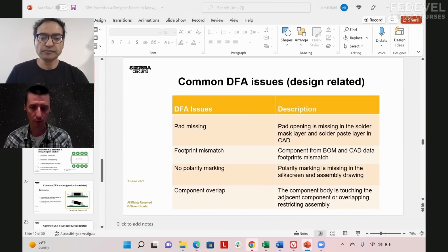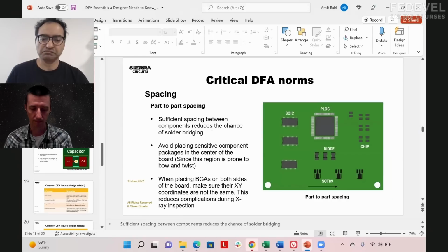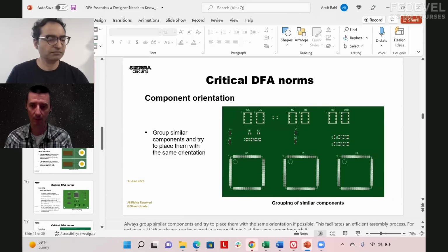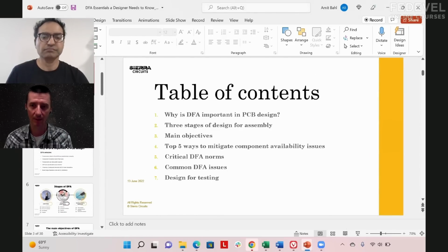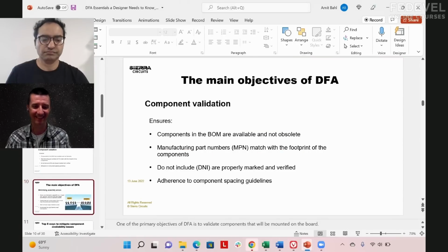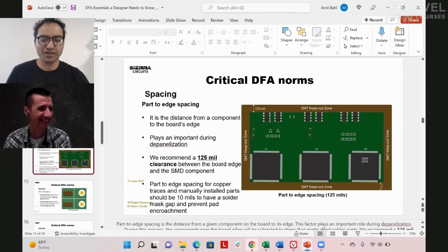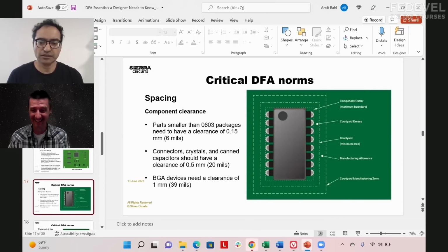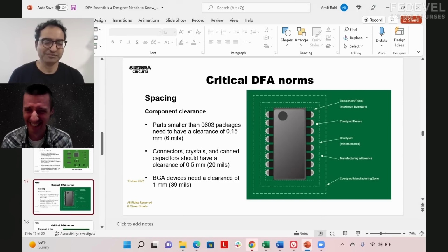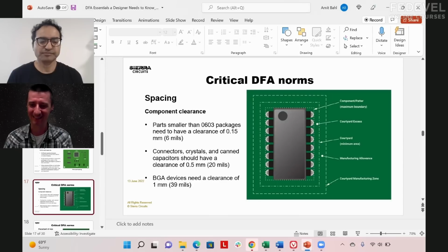So you never use the stencil design delivered from the designer. You do it based on the pads, for example. Because if we followed what the customer gives us, it'll always be wrong. Really? I should start asking what kind of changes the PCB house and assembly house always make. Then I could make more YouTube videos.